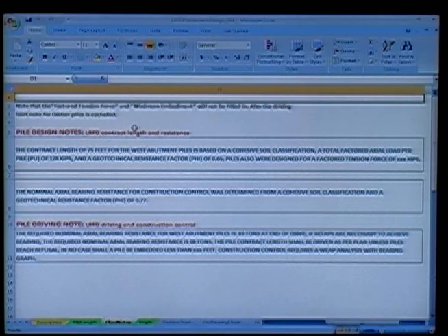And then down to what the contractor wants to know. I've got to hit 83 tons for the west abutment piles at the end of drive to achieve bearing. If I don't, I've got to get 98 tons. I didn't put in the 1 day, 3 day, 7 day because he's got to hit 98 tons. That's what's controlling. It doesn't matter what day he's trying to get that. He's got to get it if he doesn't get end of drive, and unless the piles reach refusal, and so on and so forth.